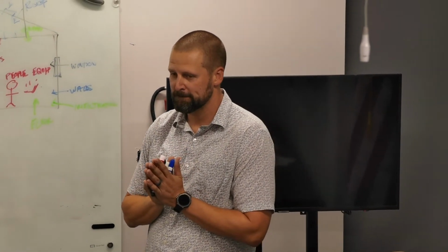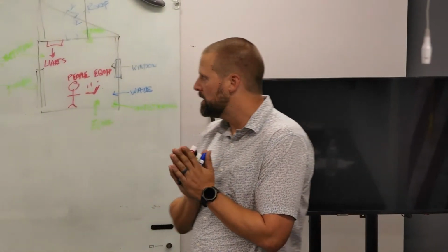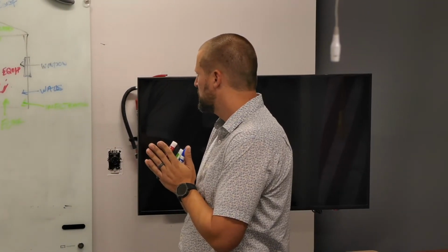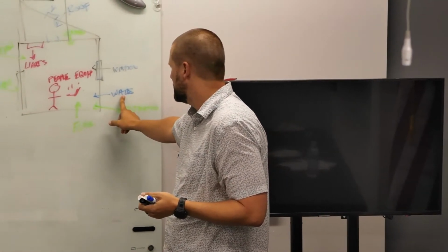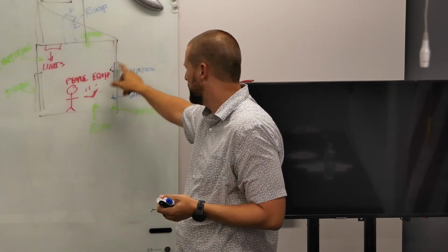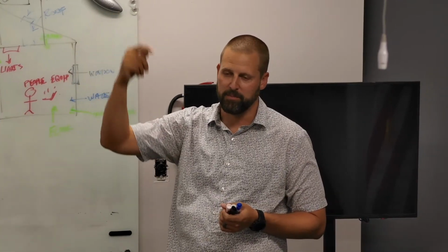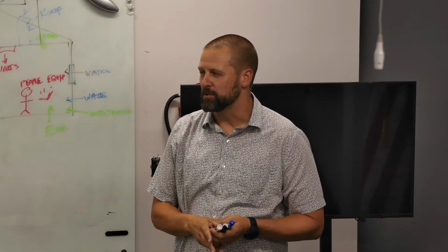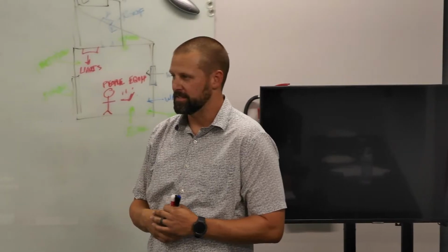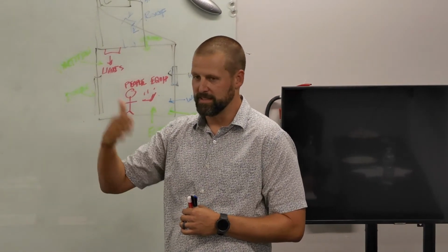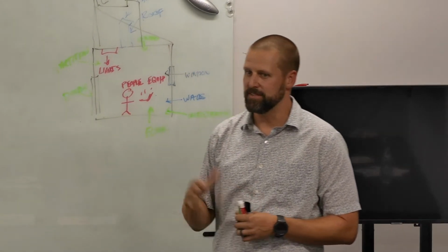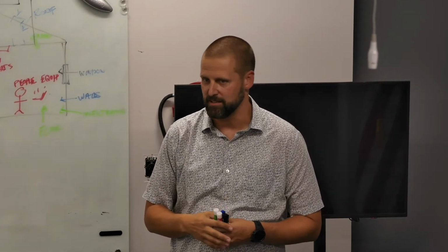Okay, anything else I missed? Any questions about that for cooling? Yes? What are we considering partitions again? So a wall is something between the conditioned space and the outdoors. A partition is an interior wall that might be conditioned. The only time we really account for them is if it's a wall between a conditioned and an unconditioned space, and even then, they're not a huge part of the load.